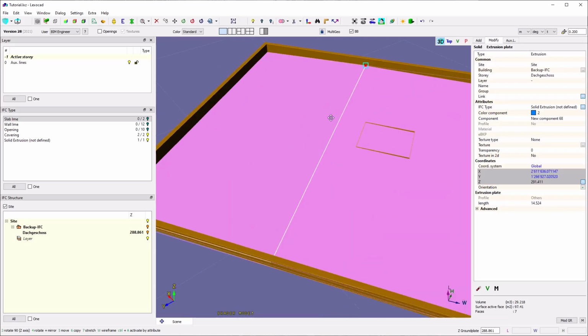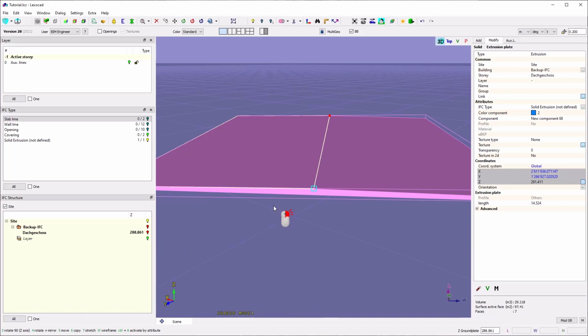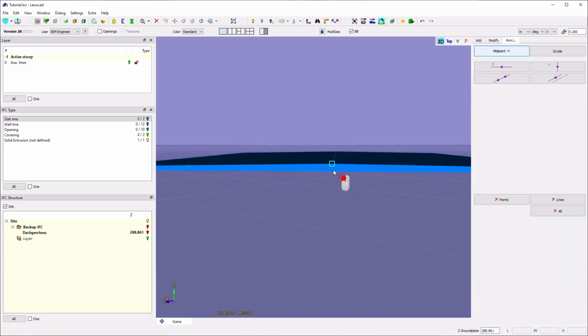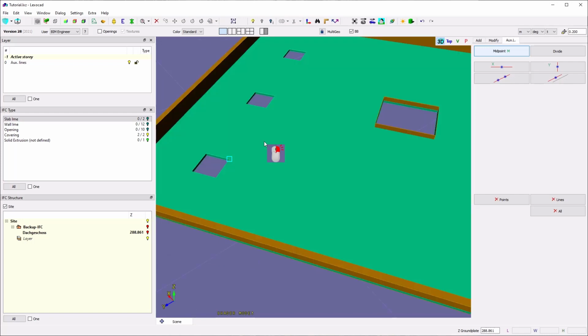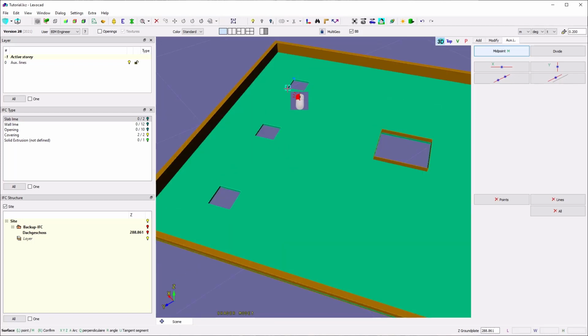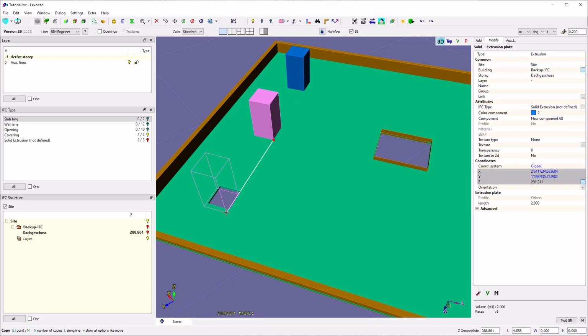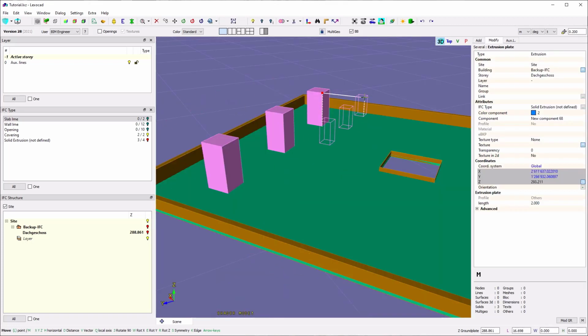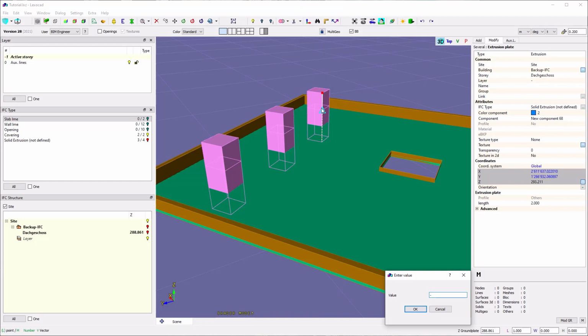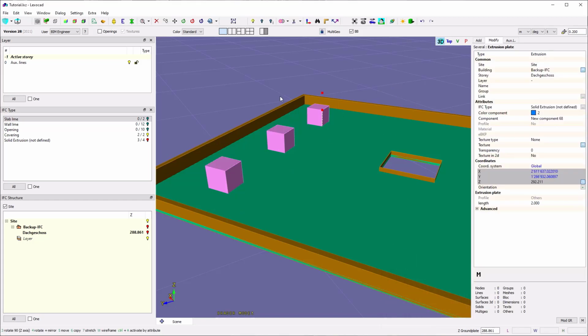But the problem is, or the good thing is, that we have now our angle for the slope, but we don't have the holes. So we make quick a surface here, make an extrusion out of it, 2 meters, copy that to the other holes, they are all the same, and move it with the key 5, and then with Z we can move it vertically. So we go just here a little bit, or we can also add a value, like I can type a number on the keyboard, or the minus symbol, so say -1 meter, or go OK, and then we got it.